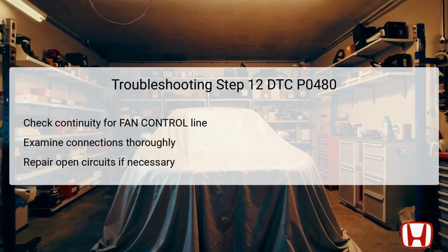If continuity is absent, it suggests an open circuit that would impede effective fan control operation. In such cases, immediate repairs are necessary to rectify the issue in the fan control line, enabling the proper functioning of the radiator fan system.